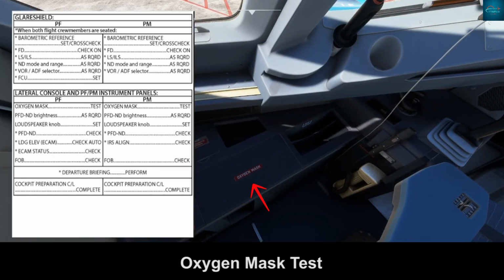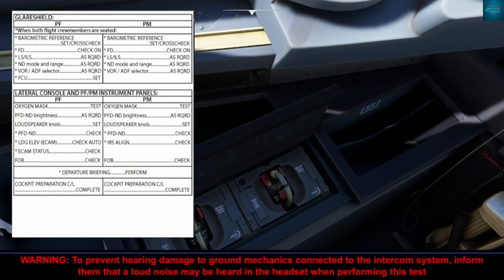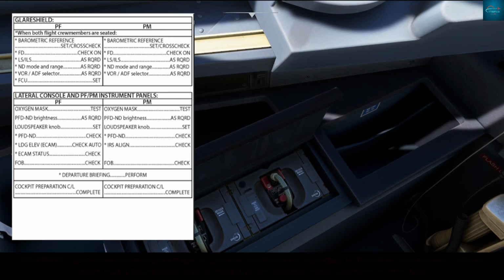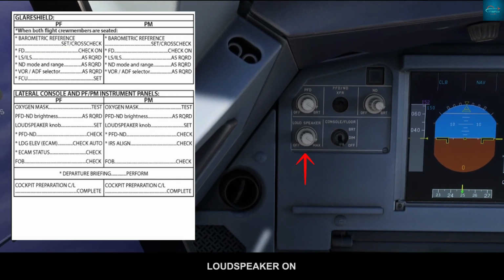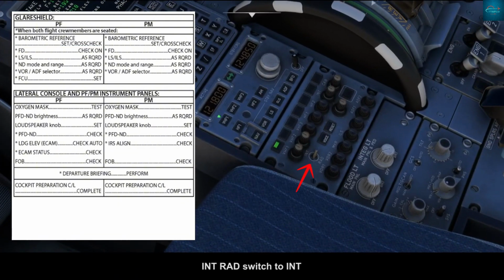Oxygen mask test. To prevent hearing damage to ground mechanics connected to the intercom system, inform them that a loud noise may be heard in the headset while performing this test. Cruise supply push button, check, on. Loudspeaker, on. Interphone radio switch to interphone.